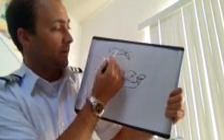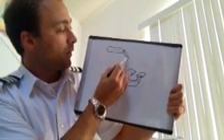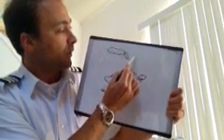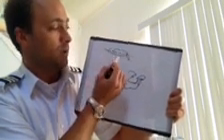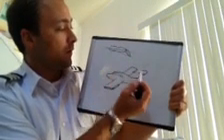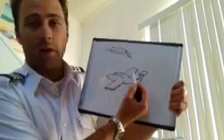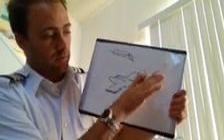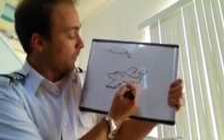We can see how it has an increase in camber and also an increase in angle of attack, as opposed to if the flight control was just in its neutral position. So what this is going to cause on the aileron that's lowered into the wind on the right for a left-hand turn is an increase in lift, causing the wing to raise.